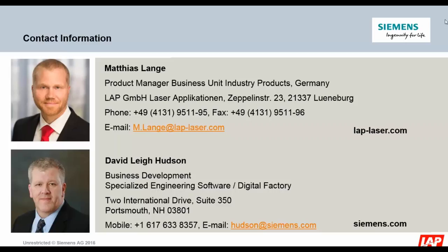Yes, the lifetime of the diodes is 30,000 hours, and the service is on a yearly turnus. Okay, next question. What is the precision of the laser scanner, knowing that the tolerance, especially in aerospace, is very tight? The CAD-PRO accuracy is 0.1 millimeter per meter distance to the projector. Plus minus. Okay, plus minus 0.1 millimeter per meter.